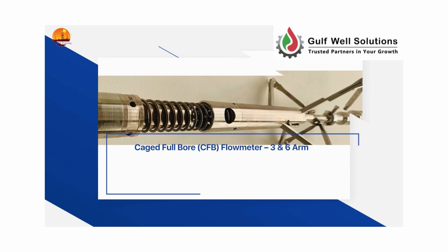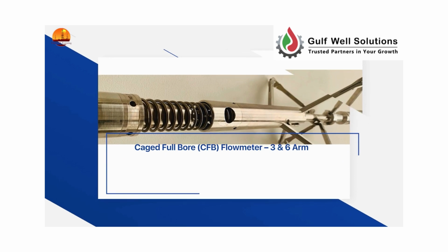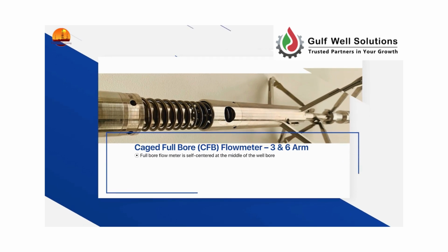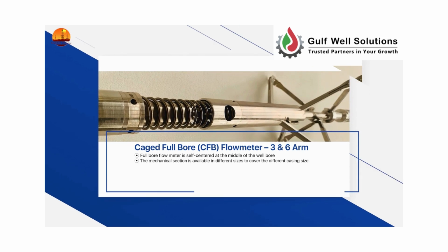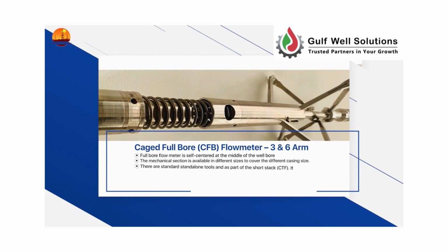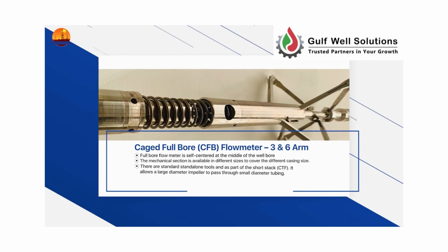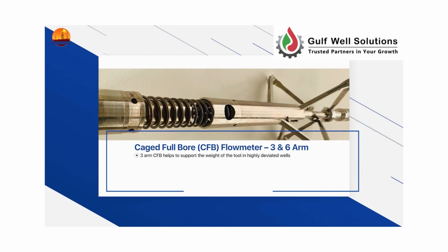Cage full bore, CFB, flowmeter, 3 and 6-arm. The full bore flowmeter is self-centered at the middle of the wellbore. The mechanical section is available in different sizes to cover the different casing sizes. There are standard standalone tools and versions as part of the short stack, CTF. It allows a large diameter impeller to pass through small diameter tubing. The 3-arm CFB helps to support the weight of the tool in highly deviated wells, acting as a centralizer.